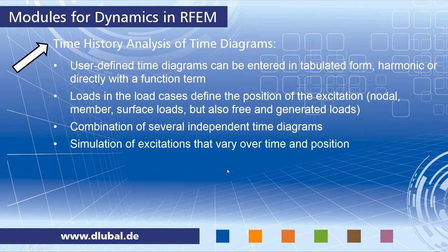We can do time history analysis of time diagrams. Time diagrams are user-defined excitation functions, and you can either enter them in a tabulated form, for example importing them from Excel, or you can define harmonic functions where you have to provide an excitation frequency and a shift, or you can enter a function term directly, and this is what we want to do today.